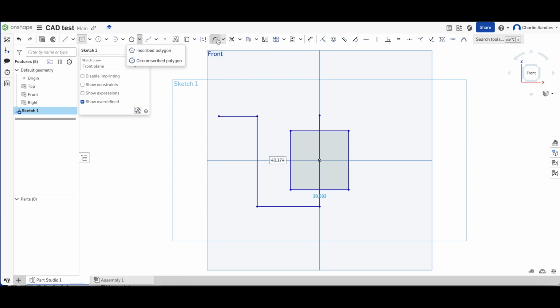We have something called a sketch fillet, which if I select, you'll be able to see that I can select two lines where I want to create a filleted edge, so a curved edge, and you can see that I've got this large arrow here that I can pull back and forth to change what the radius of that corner is. Now, if we just have a look at this, once I pull it past a certain point, you'll see that this curved line here has changed from blue to red. So if I just pull this back again, we're at blue, and now it's changed to red